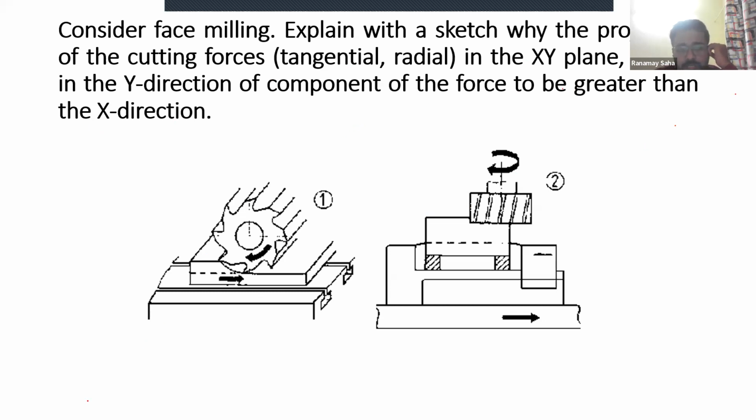So you can see here that this is the rotating tool. This is the milling case, by the way. And this is a milling cutter, and this is a slab milling happening here, or face milling, you can say. So this is the cutter direction. Tangential to that, we find the cutting force, Fc, and perpendicular to Fc, we get the thrust force.